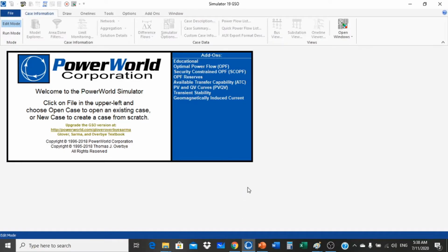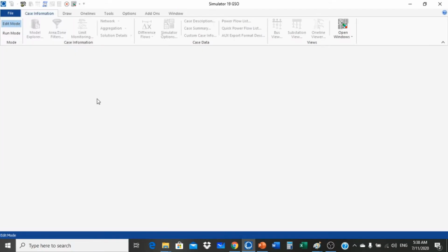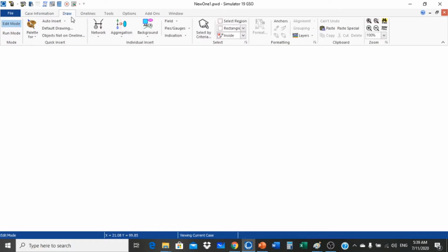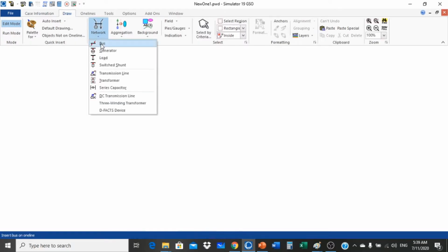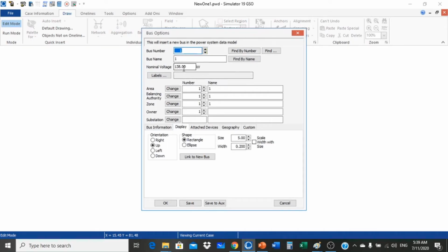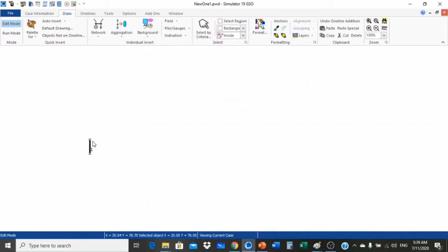And also we plot how the megawatt variation happens in the system. Now we verify the result using PowerWorld Simulator, how the transient response is when the fault occurs at bus 4 of our system. Now we select File, go to New Case. Now we draw our model first. Select bus 1, which is operating at 11 kilovolt.